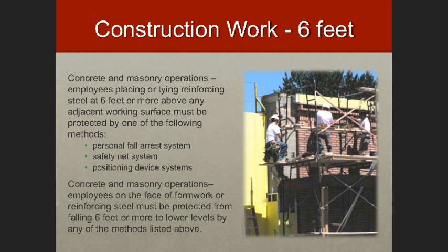Construction work, again, as we mentioned in some of the other modules, is going to require a 6-foot standard for fall protection. So generally speaking, anytime an employee working in construction has the potential to fall more than 6 feet, then we look at some kind of fall arrest system, safety net system, or positioning device system.